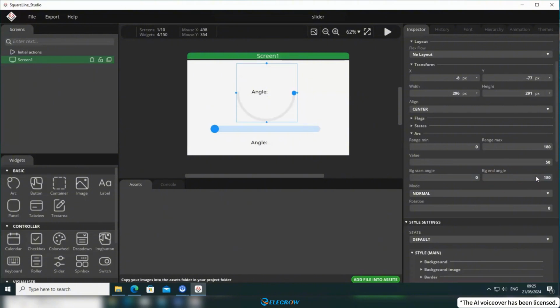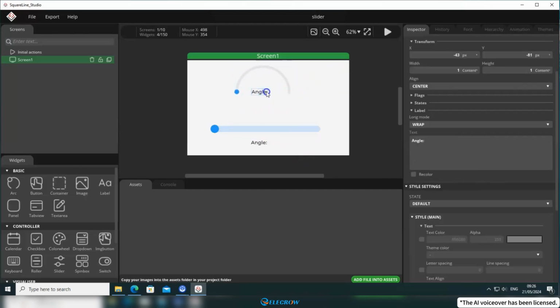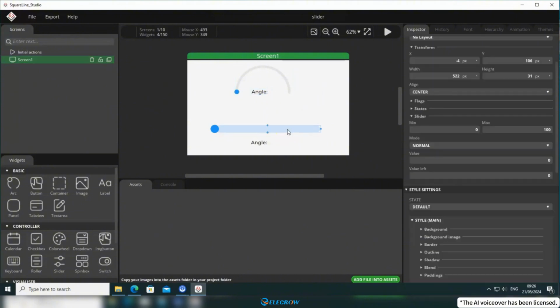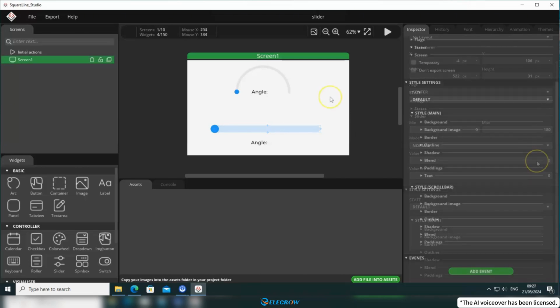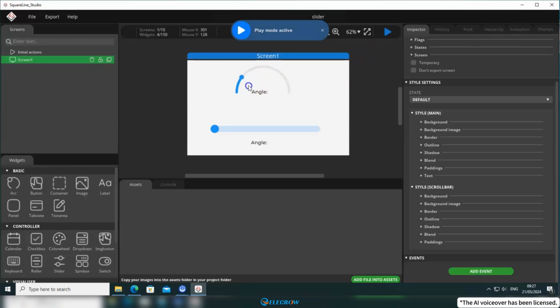At this point, you may find the circular widget's usage feels a bit unnatural. Don't worry, just find the rotation section where you can adjust the direction of the circular widget. Rotate it 180 degrees, and that's it. Then you can adjust its size accordingly. Next, let's set a range for the value of the slider widget to match the rotation angle of the servo. Finally, conduct another simulation, and if there are no issues, you can export the UI file.